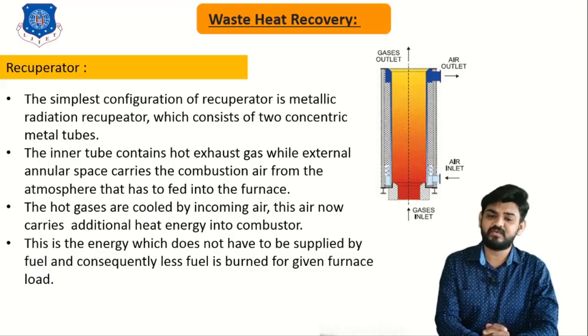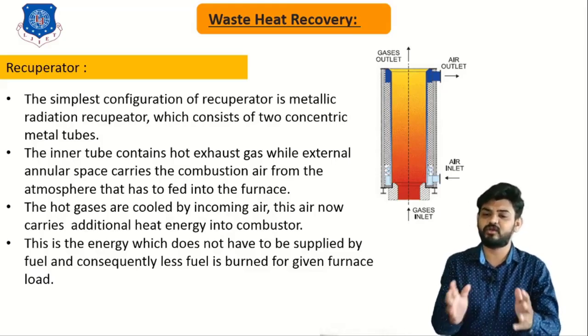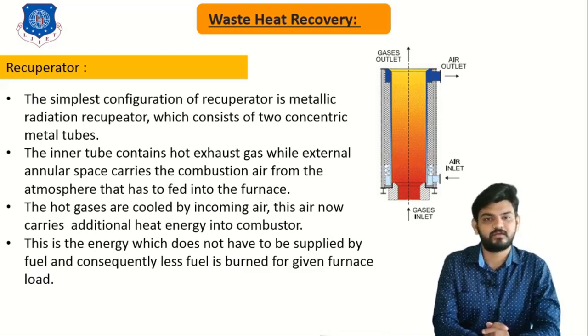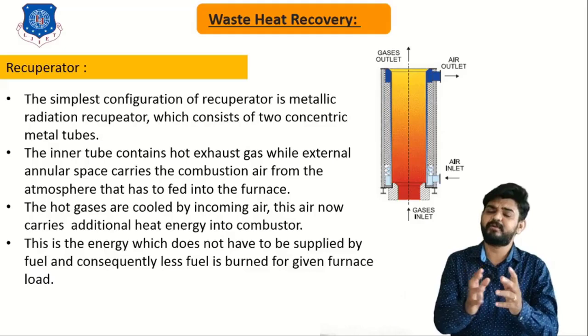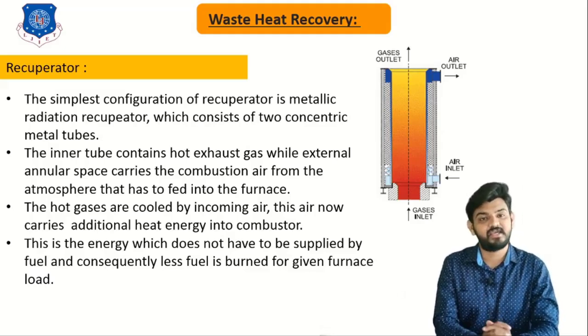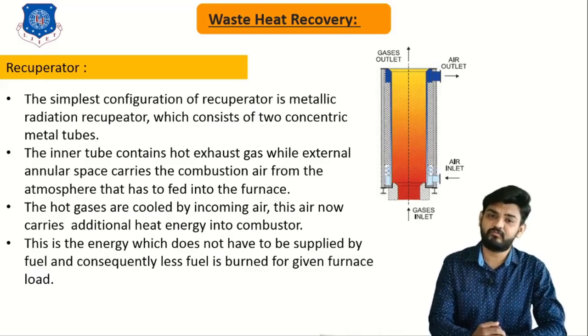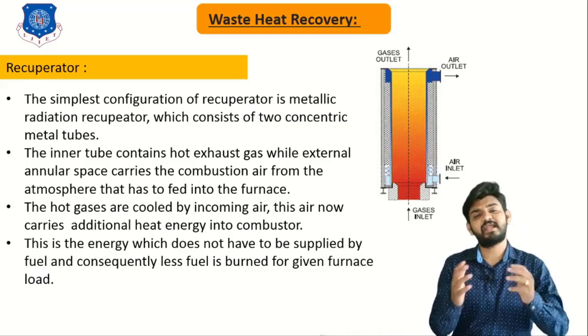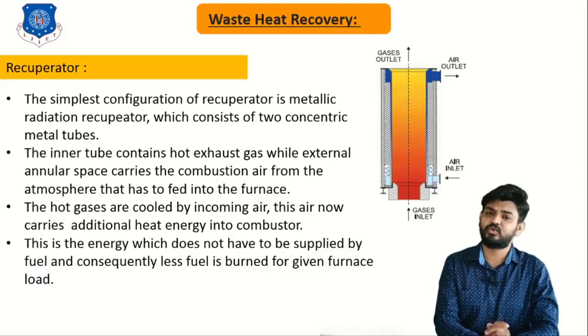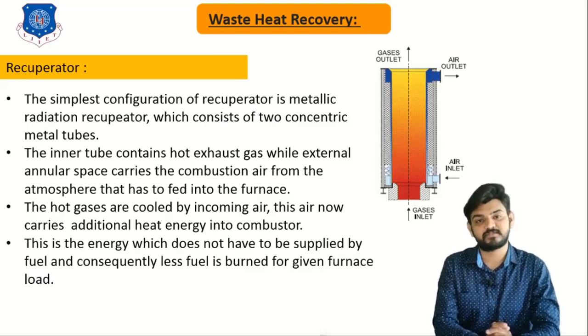This is energy which does not have to be supplied by fuel, and consequently less fuel is burned for the given furnace load. So, by means of recuperators, we can achieve a significant amount of energy efficiency and reduce the consumption of fuel, since the energy required for preheating the air will no longer be required. So, this was all about the recuperators used for waste heat recovery systems.